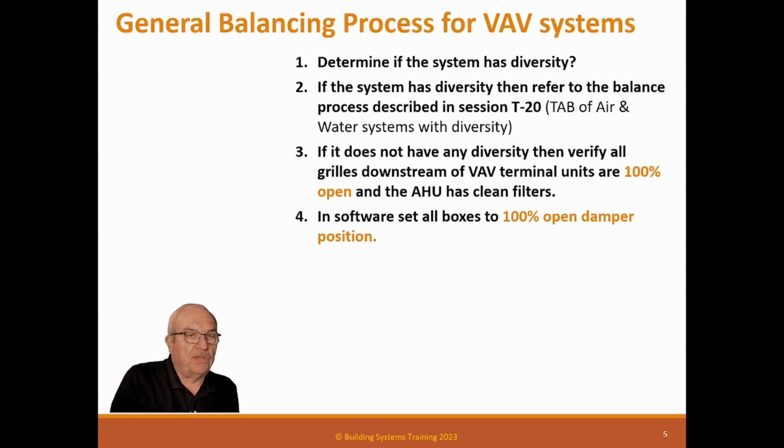In software, set all boxes to 100% open damper position. So you want to do this in software. You just command the box to open the damper 100%. It knows how to do that, it's no problem, and it will stay that way as long as you have that command in place. Now, some people try to play with this differently.